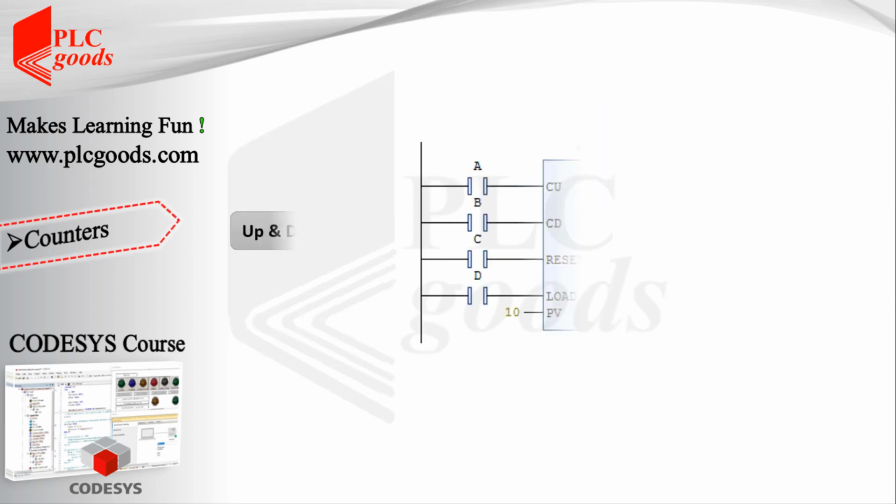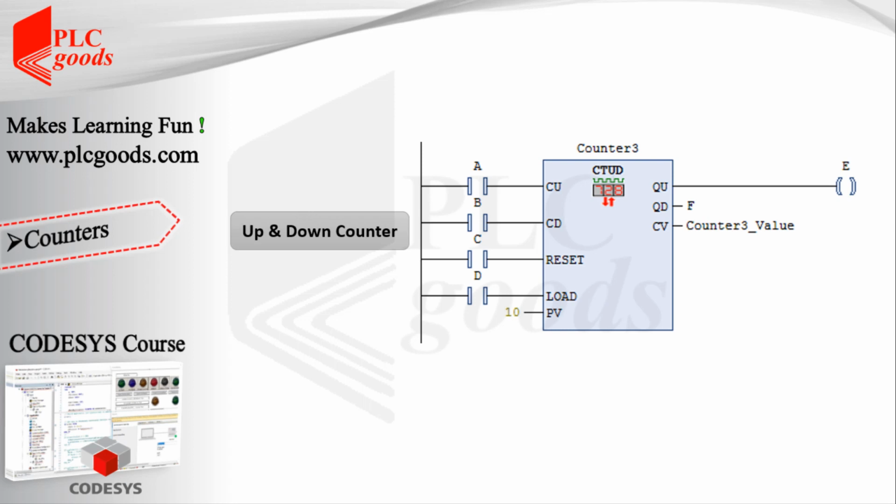Note that, a rising pulse on the load input will send the PV value to the counter value. At last, the up-down counter can count both up and down. As you can see, it has a bit more pins than the two other counters. It has two count inputs, one for counting up and one for counting down. The reset input will reset the counter value to 0. The load input will send the PV value to the counter value. The first output will be on if the counter value is equal or greater than the PV value, and the second output will be on if the CV value reaches 0.